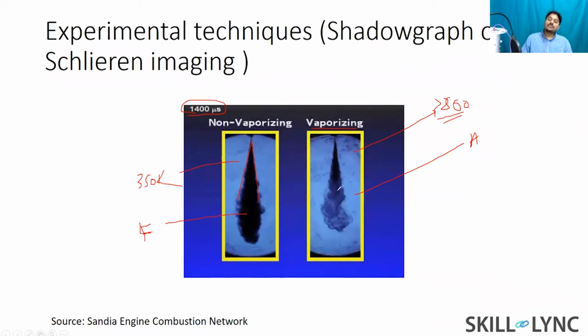The reason why you do this type of study is, well, you measure all the critical information that you want. And then you take this experimental data and use it to validate your simulation results. This is called the process of validation, because if your CFD simulations need to be accurate, they need to capture all the trends that you see in real experiments, correct? That is why people take this type of data.